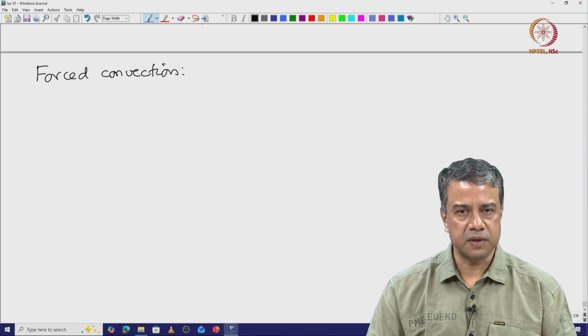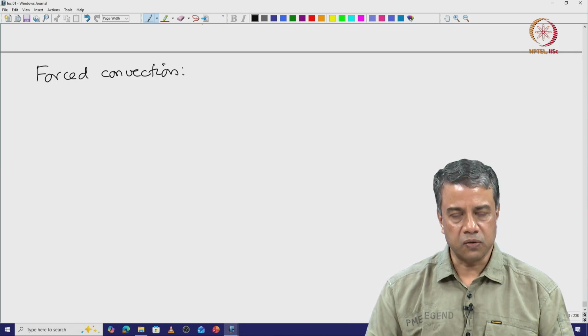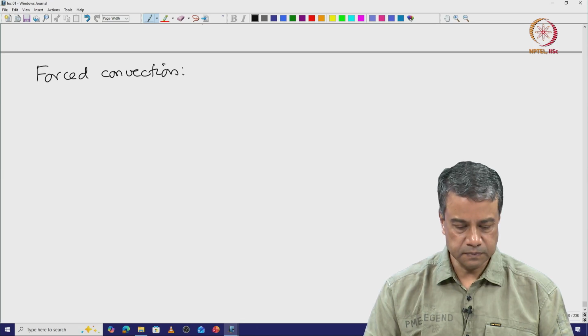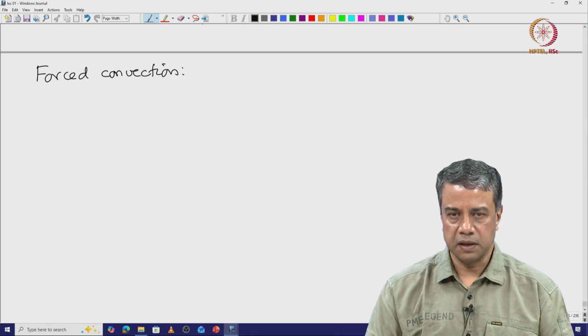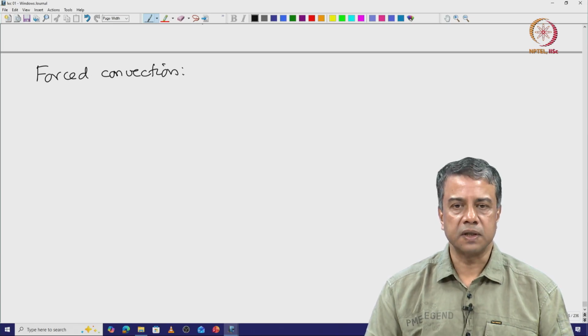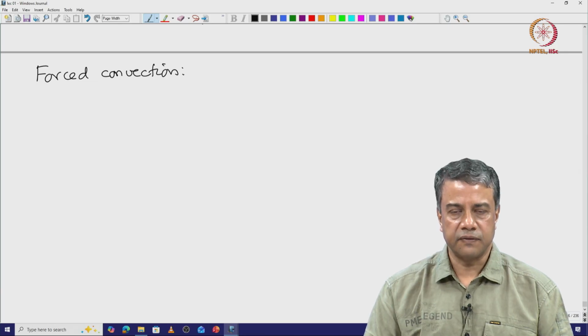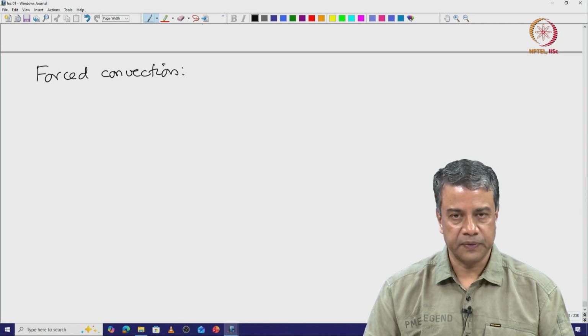disturbance due to the temperature field due to the heating from the surface in the limit as the Peclet number becomes large. In the limit as the Peclet number becomes large, the boundary layer thickness becomes small in such a way that convection and diffusion continue to be comparable in the boundary layer even as the Peclet number is increased.